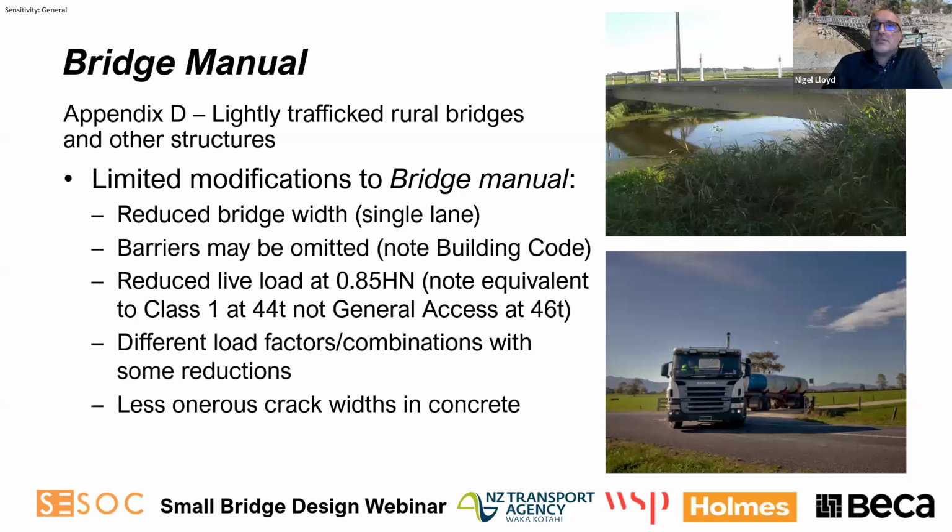So for small bridges, it's not going to be a problem. HPMV is a different matter. It's possible that vehicles may be serving a particular HPMV route, and it could be the milk tankers are serving an HPMV route, then they need to be designed to a different loading because they have a heavier individual axle load.